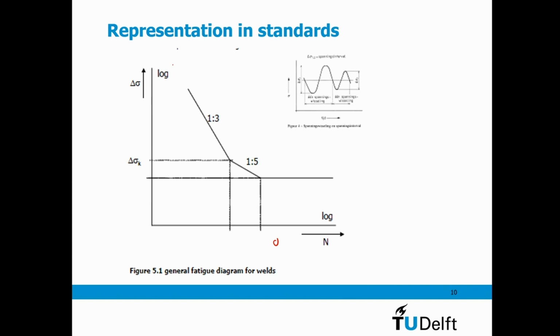For fatigue, this is much more complex, because if I have a reduction in stress, I can also end up on another part of the slope with different consequences. Or even better, if this is my stress here, and then I have a certain fatigue life, if I drop it slightly, then I am in the infinite life zone. So this curve, as a consequence, is that calculations of what happens if I have a lower stress can only be answered ballpark ways.